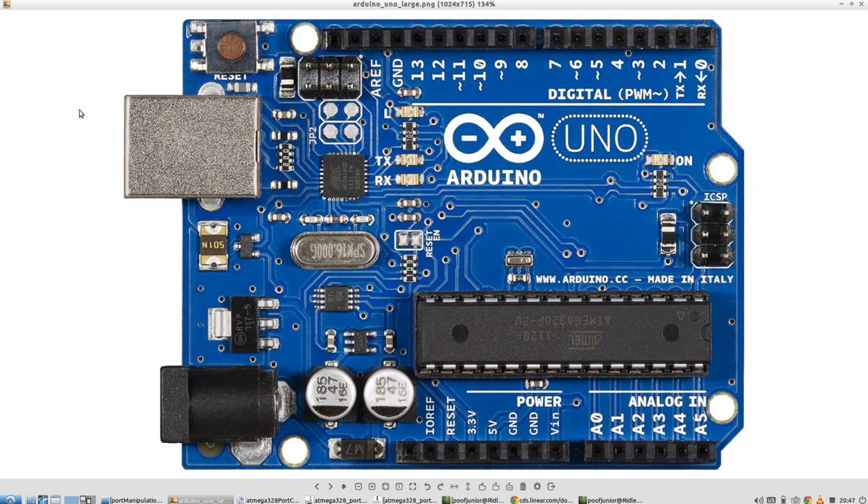So what we've got here is the Arduino board, and you have to keep in mind that there are electrical connections from the pins on the chip itself to the header pins out here. So you can plug your electronic circuit into these on the top and bottom, and those are mapped to the pins over here. It's not quite one-to-one, so 0 is not going to be this corner, 1 is not going to be over there. It's a little bit spread out, and the designers did that for distinct reasons that we'll probably talk about later. But just have an understanding that these are wired physically to these pins out here and down here at the bottom.